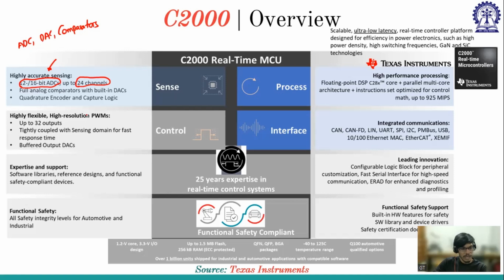They also have very high resolution PWMs, and they can give up to 32 output PWMs. You can configure the general purpose input output pins and then use them. They also have buffered output DACs and different reference designs. You can get them from their website, and you can also get many example projects, access them, and test whether it is working or not. So you can actually sense signals and also control them by writing the control. It also has some functional safety features.